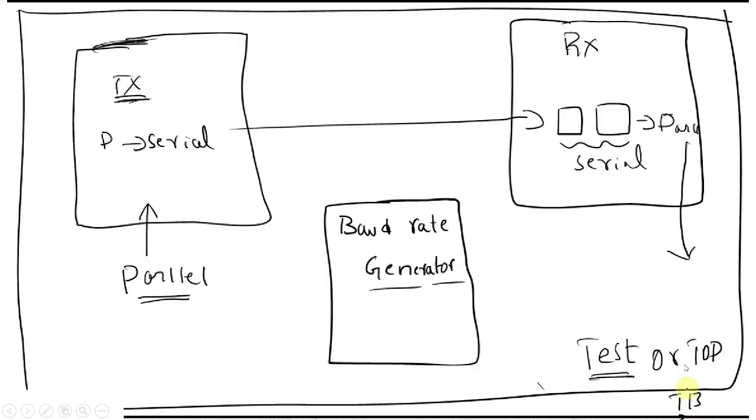So if you see the coding part, you have parallel to serial communication, and there is a baud rate generation. Under the test bench, under the top module, there is serial data. It is transmitting to the receiver, sending serially, and again converting from serial data to parallel data. So this is the basic thing we need to do.